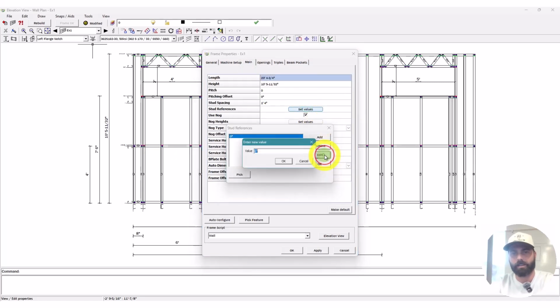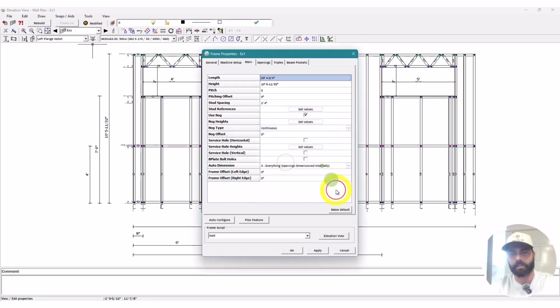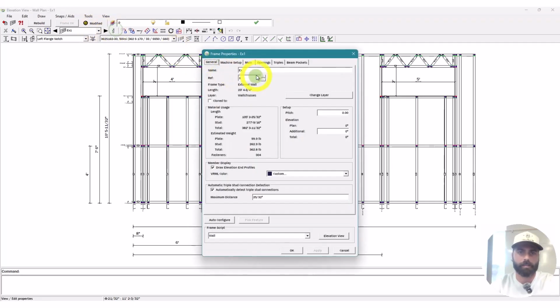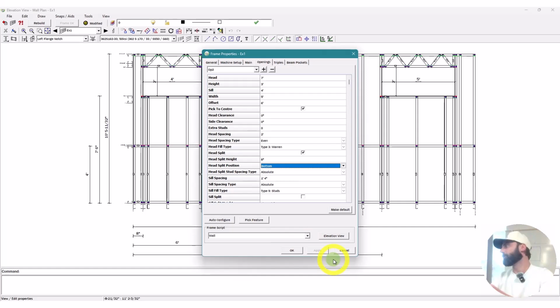So for measuring openings, opening 2, from the 0 datum of the full 24, it lines up, including the 3 5/8. So if it's a 24-foot tiny house, it should be 3 sheets of sheathing from the outside corner without any issue. So now we should have a continuous 16 inches, except for opening 3.